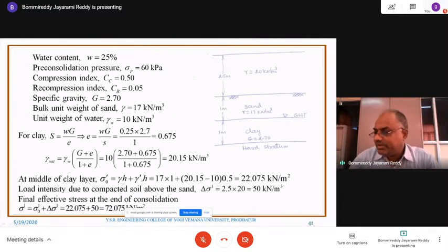So you can look at the diagram given, 2.5 meters fill is now provided with a density of 20 and 1 meter sand, 1 meter clay. And all the details are given in the clay. You need to find out all the stresses exactly at the center of the clay. So you do not know the gamma saturated for clay. Since gamma saturated for clay is not known, find out gamma saturated. To know the gamma saturated, S e is equal to W G by...